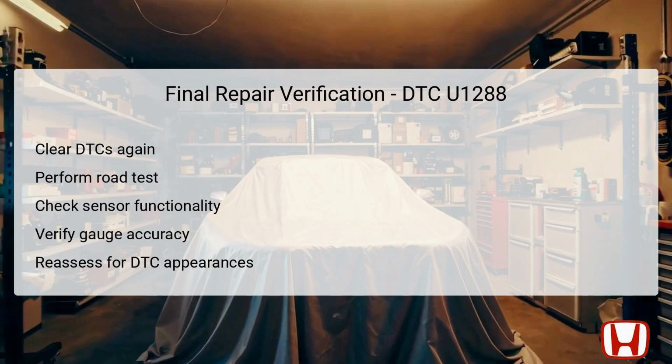Final repair verification is the concluding phase in diagnosing and resolving DTC U1288. After addressing any identified faults, it's crucial to clear the DTCs once again using the Honda Diagnostics System, HDS. This will reset the vehicle's computer, giving an opportunity to assess the effectiveness of your repairs.